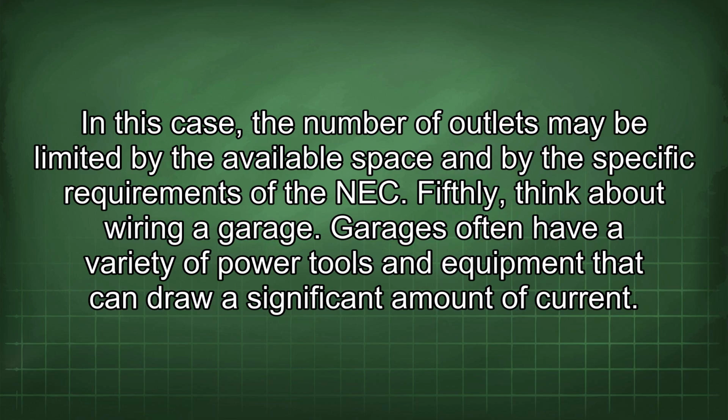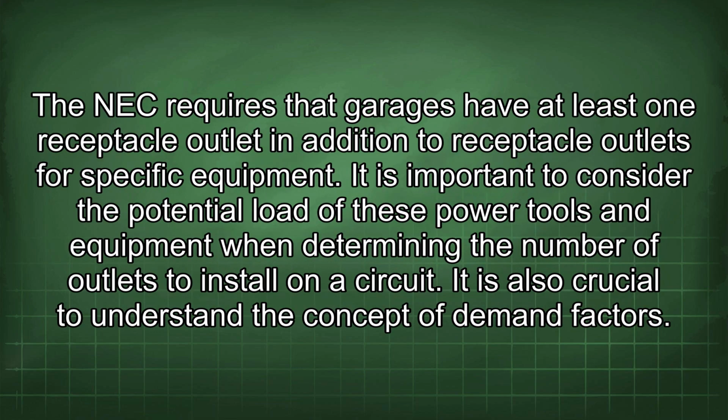Fifthly, think about wiring a garage. Garages often have a variety of power tools and equipment that can draw a significant amount of current. The NEC requires that garages have at least one receptacle outlet in addition to receptacle outlets for specific equipment. It is important to consider the potential load of these power tools and equipment when determining the number of outlets to install on a circuit.